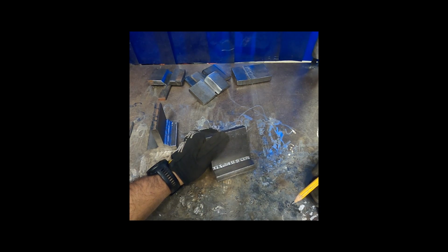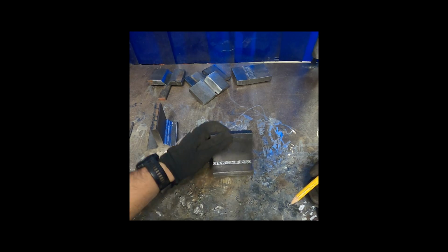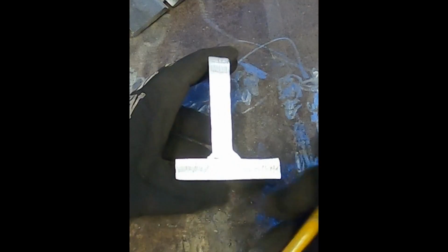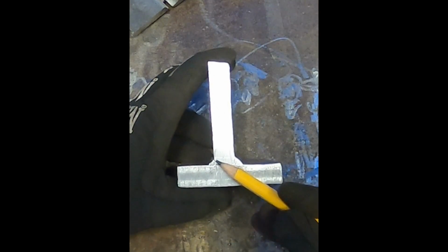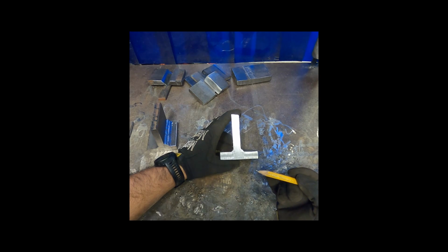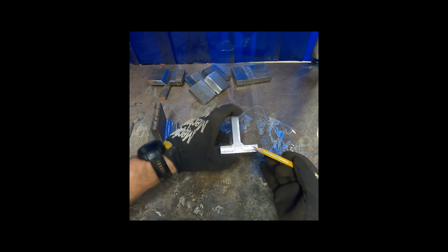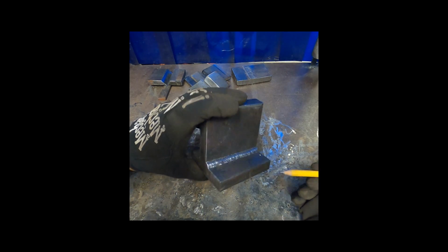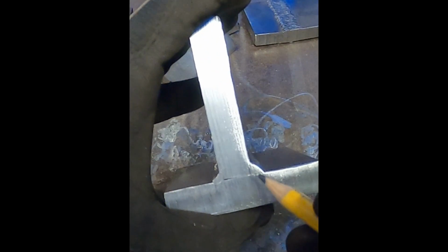So as we take a look at the first bead, I welded this using a 6010 electrode and at approximately 90 amps, and you can see that viewing it from the side, there's not much of a profile to look at. And on the opposite side, I used 7018 at approximately 135 amps. And so using this electrode, it gives us a difference in the profile.